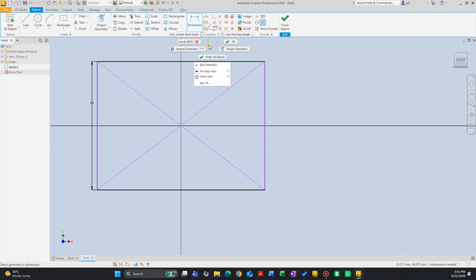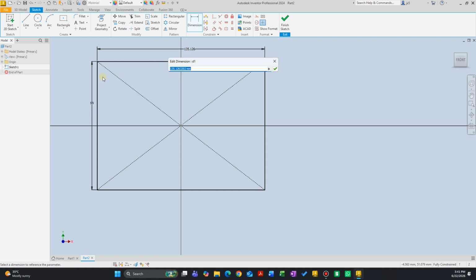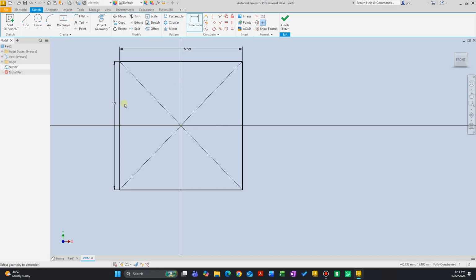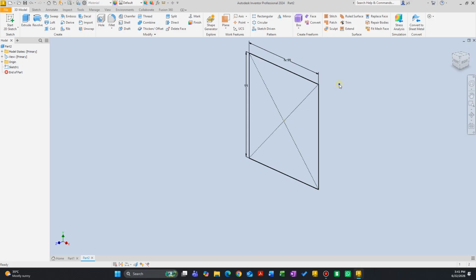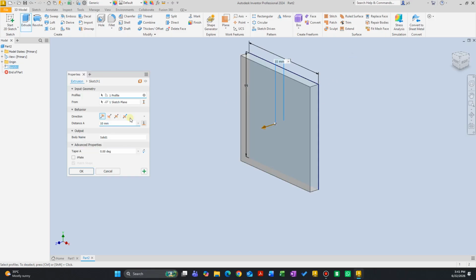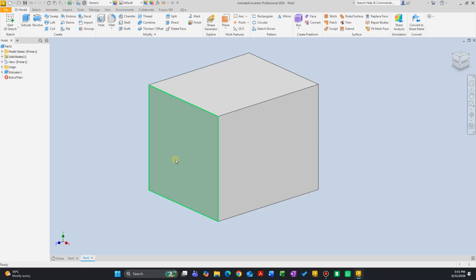And let's make this a square box, so I will also enter 99 millimeters, but I will use this 99 millimeters that I already entered, so it's going to make it easier for me. So it's 99 by 99 square. And let's finish that 2D sketch. Now extrude it, right click, extrude, and let's enter maybe 120 millimeters. So now I have my second object also designed as well.